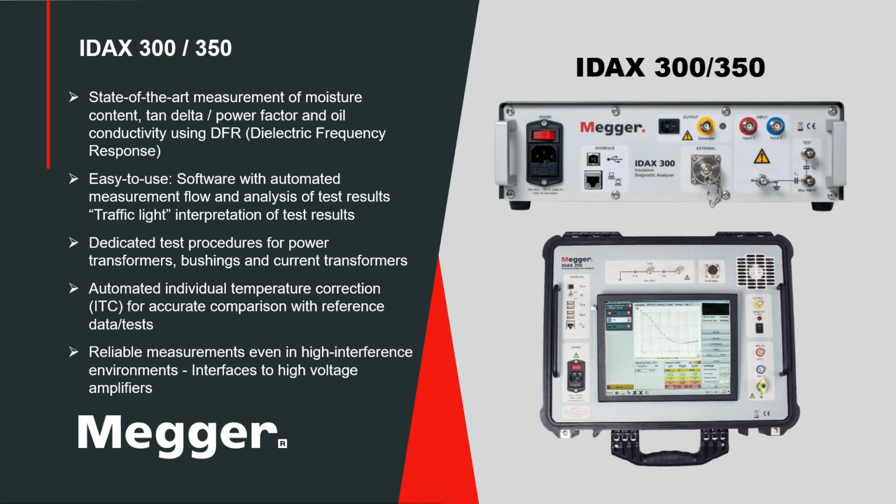There's so much information that we have learned from dielectric frequency response testing. This is state-of-the-art measurement of moisture content, tan delta, power factor, and oil conductivity based on this frequency domain response. It's very easy to use. As you could see, the software is pretty much automated, it gives you the information, provides you with assessment, and has this traffic light interpretation of results. It has dedicated test procedures for power transformers, bushings, and current transformers.